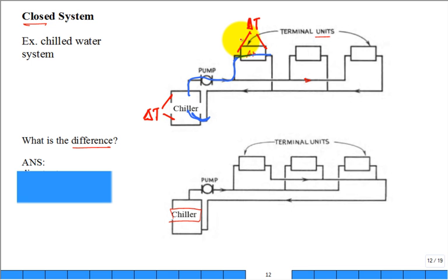Because once it goes through that first air handling unit, does it then go to the second air handling unit and then the third? No, it'd already be warm. It needs to get back to the chiller and be chilled, right? So it doesn't go in series through the air handlers. It's really what's going to happen now that it's after. So after, where does it go? Isn't that the route back?